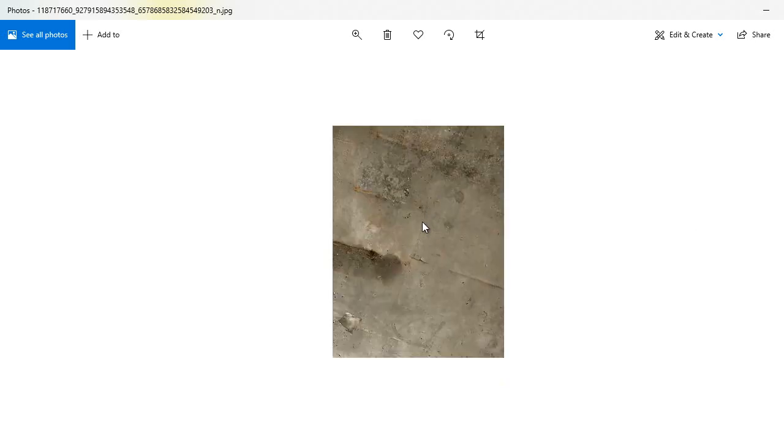What happened is that they did not provide the required thickness to the slab. It needs 7.5 inch thickness from the ACI provision, which I calculated, but they actually provided roughly 6 inches. So they provided 1.5 inch less thickness to the slab system. That's why the slab system is cracked.